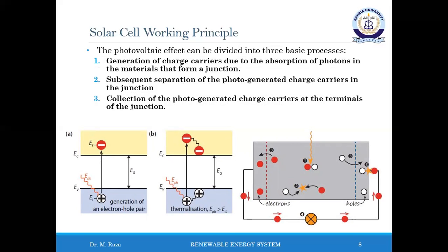In a real semiconductor, the valence and conduction bands are not flat, but vary depending on the so-called k vector that describes the crystal momentum of the semiconductor. If the maximum of the valence band and the minimum of the conduction band occur at the same k vector, an electron can be excited from the valence to the conduction band without a change in the crystal momentum.